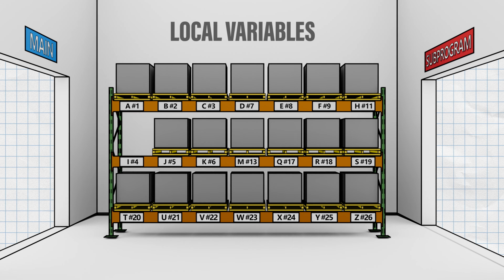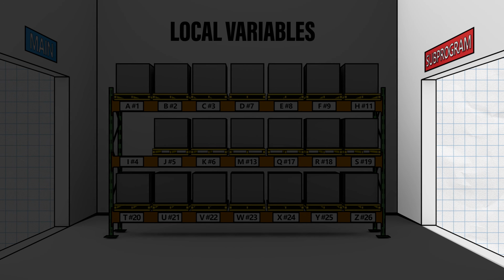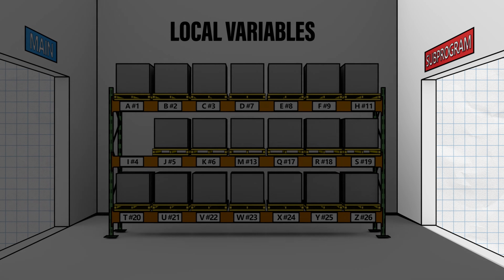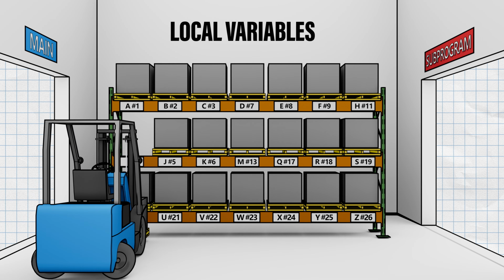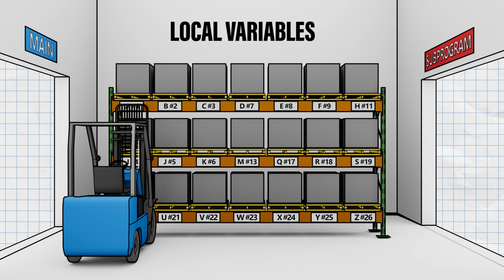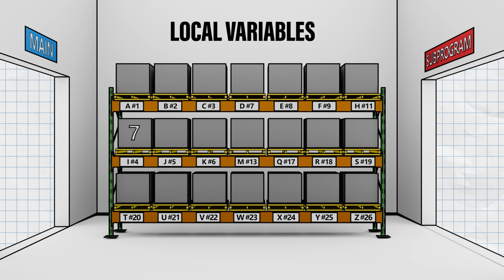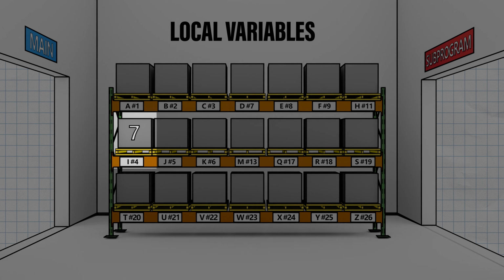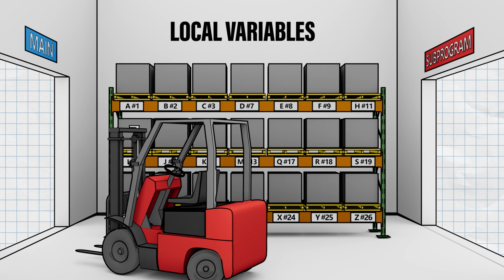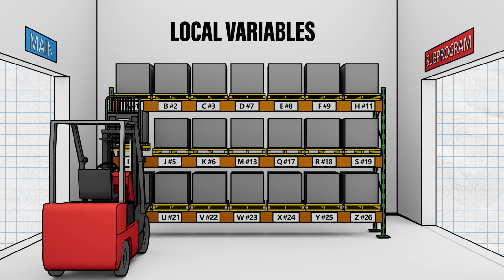Check out this graphic. On the left, we have our main program. On the right is our subprogram. The way this works is our G65 drops off information, input variables, onto a local variable shelf, like our I value, I7.0. Later on, when our subprogram is called, our subprogram is going to go to that exact same spot on the shelf.